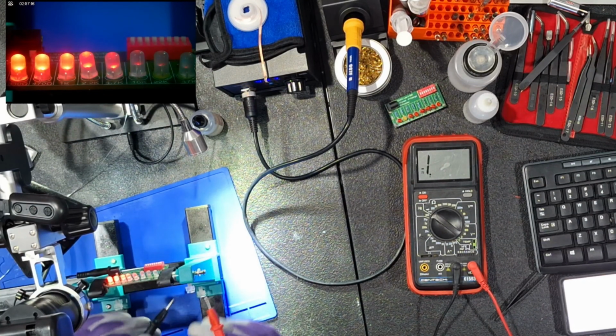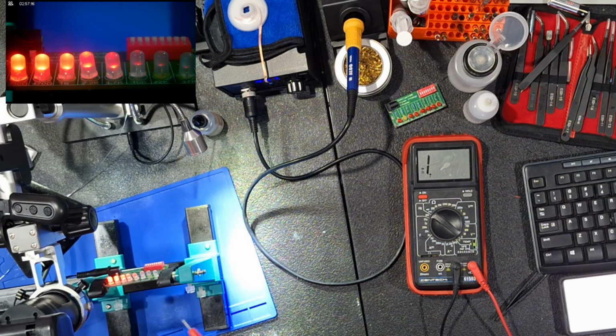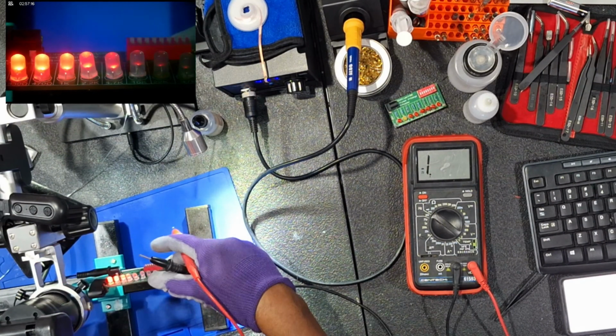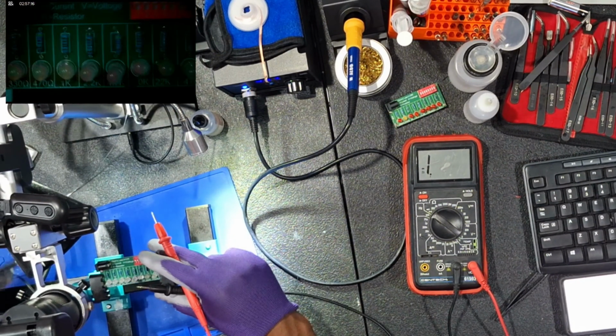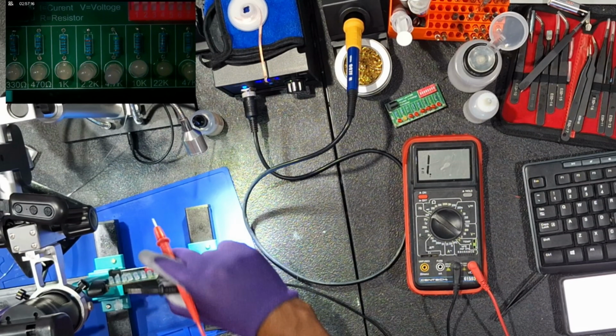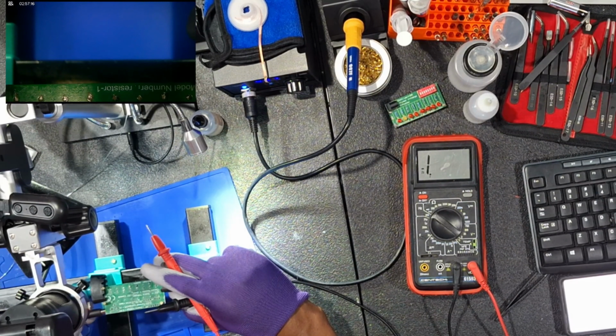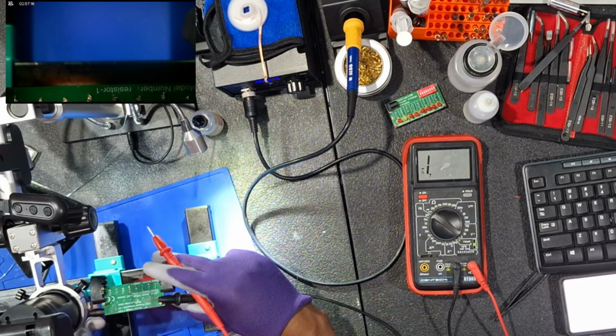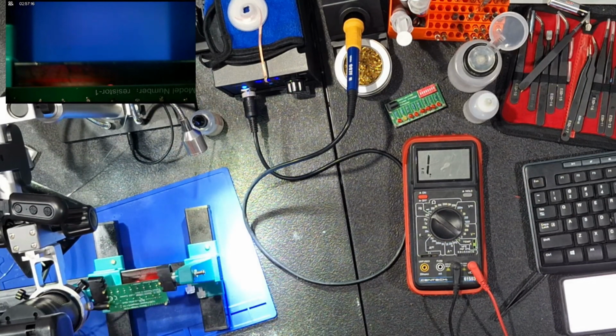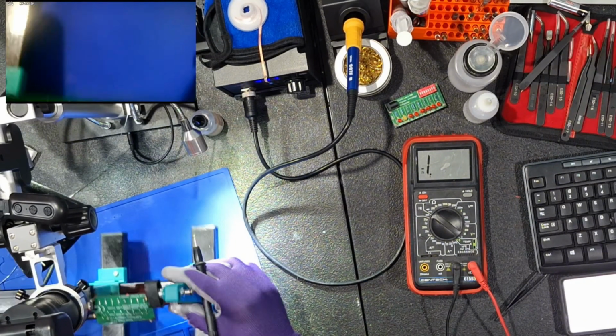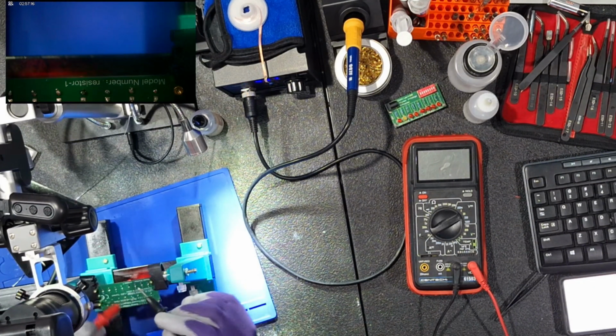It's kind of difficult to test current from this point because normally you have to break the circuit and let the current run through the multimeter. So it's easier to test voltage, and resistance is actually restricting current flow, but it also gives you a drop in voltage. So right away you know that the resistor is working, and these are connected using a 9-volt battery, and they're not burning up as I did demonstrate earlier.